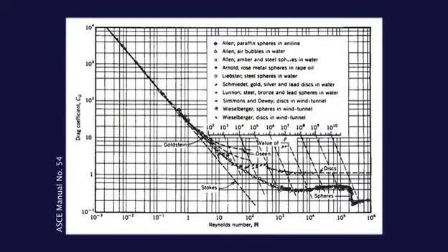For particle Reynolds numbers greater than 0.1, the drag coefficient is still a function of Reynolds number, but the relationship cannot be expressed in analytical form. The relationship of drag coefficient versus particle Reynolds number is shown in this figure.